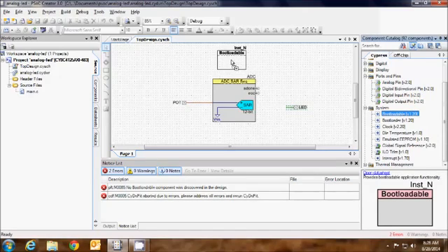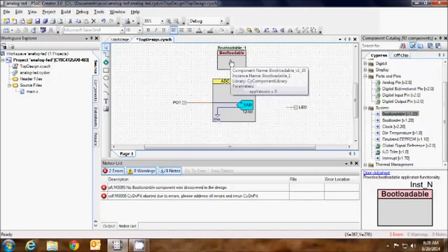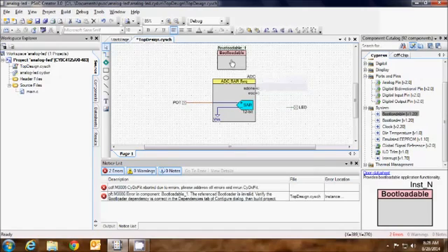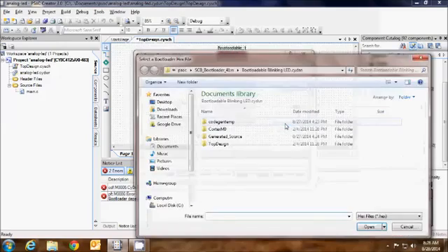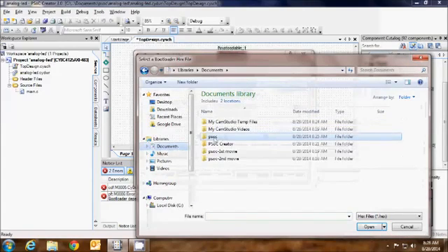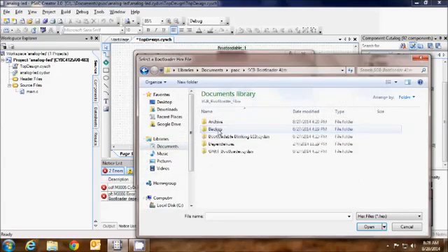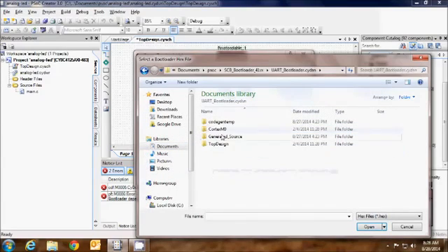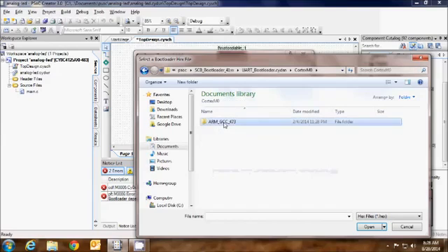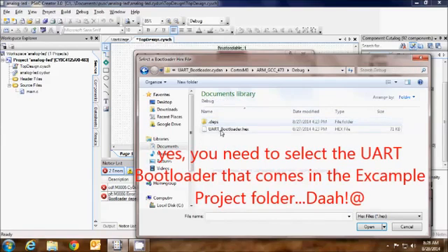There it is. And the thing you have to configure in that is you have to point it at the hex file, the actual executable file for the project. So in that you've got to go find the project. It's under PSOC and it's called Analog LED, I think I called it, and not the bootloader one, but yes, the bootloader one. Okay, I've got to fix that narration.